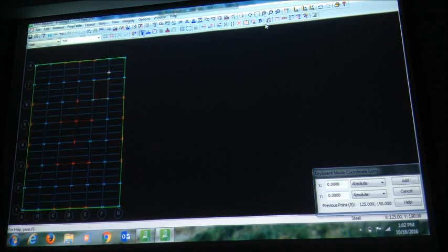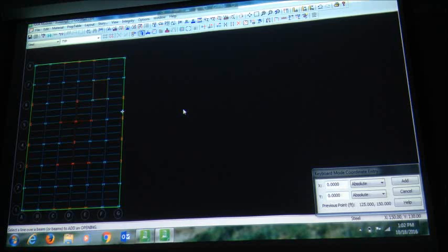Okay, so far we are okay. The only thing I am not showing you, because these are moment frames, is the beam to column connection, which is fine. But these are brace frames and I have not given the braces yet. I have to give the braces when we have an elevation. Right now I'm just giving the typical floor, one floor level. I do not have an elevation view, because the multiple floors are not there yet. Once we add the multiple floors, then I will give braces for elevation.